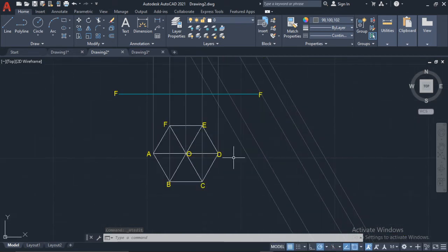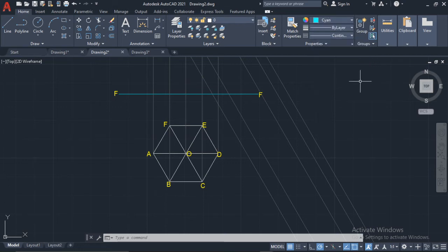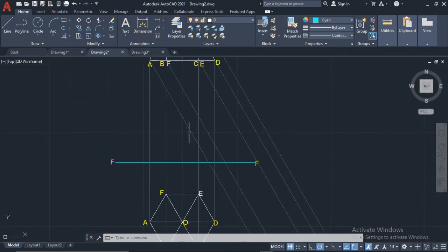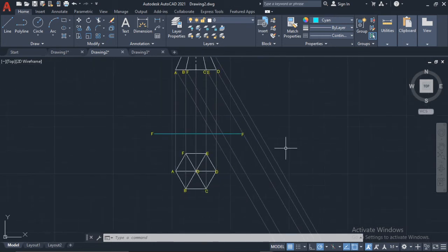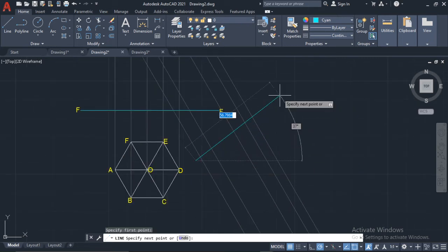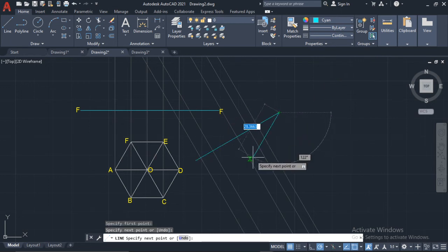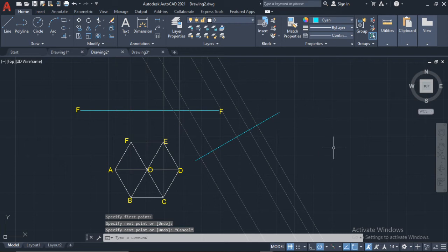So now we have a perpendicular bisecting line. And that line is going to be our X1, Y1 line to give us a different view plane. So you have the plan view and this view plane. The XY line separates the plan view from the front view, and then the X1, Y1 line will separate the front view from the auxiliary view. So we'll have our X1, Y1 line. We can draw it anywhere. I could draw it here or up here, anywhere. So I can draw it right here, and it will be at that angle. Yeah. So it bisects it perfectly like that.